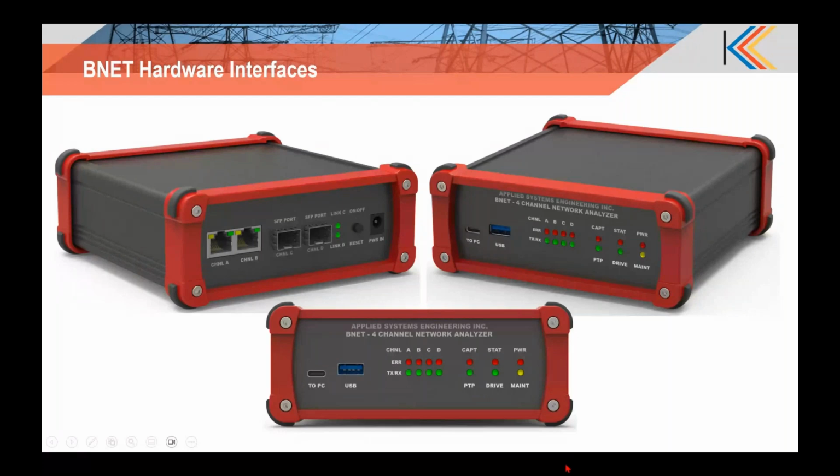All right. And how many IEDs or tags can be supervised or subscribed to? What's the number of IEDs? Okay, so we don't have a limitation from the number of tags perspective, but the test set is primarily used for troubleshooting purposes. So from that perspective, we expect the user to load, say, in the range of 10 IEDs in the test set and simulate or troubleshoot that environment.